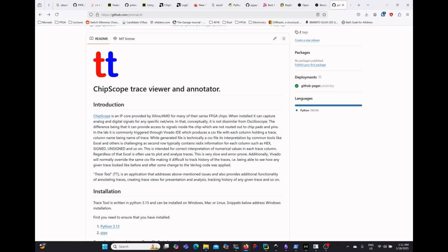your FPGA design. In that, it is similar to the oscilloscope. The difference is that it allows you to access signals and wires of your design that are not routed to the external pins. This is extremely powerful. Similar to the oscilloscope, it exposes the concept of a trigger, conditions that activate the trigger, and a set of signals, i.e. traces, that are to be captured.